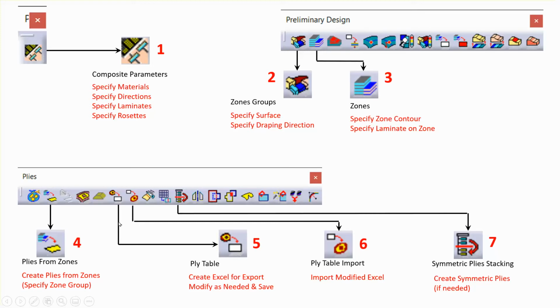So export Excel, import Excel, and so we're going to have the 8 plies ordered in the way we want, and then we use the symmetry in order to create the mirror of that. So this is a strategy we're going to be following. So in fact, this first video segment is creating geometries, very simple, and then following the scheme, and creating the composite panel, and then video 2 is going to be a buckling analysis of it.